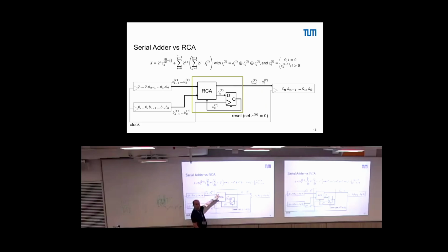This adds up the two numbers and results in a sum bit plus a carry bit. So we have the sum bit, that is done. The carry bit is fed back into the register. And if we have a ripple carry adder that has a full adder as an input, we can take this carry bit directly into the next ripple carry round and apply exactly the same hardware on the next, let's say, 8 bits or n bits. And we do this again and again until all our data chunks are processed and are ready.